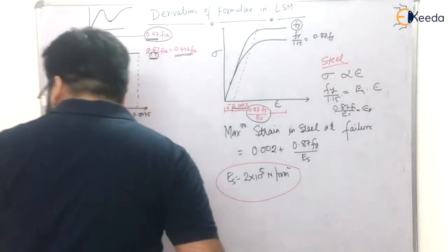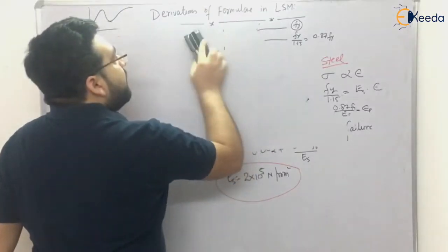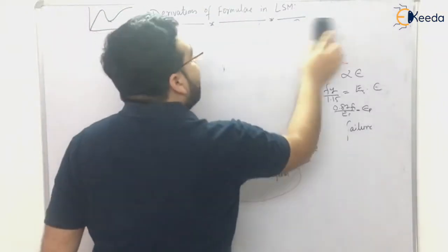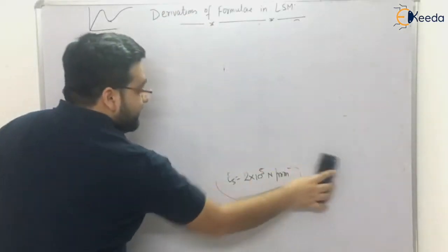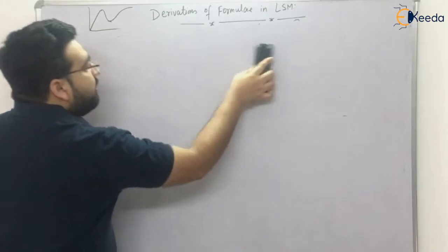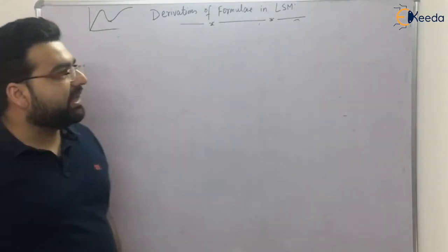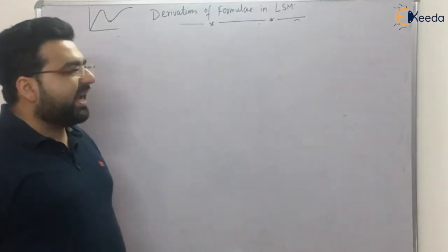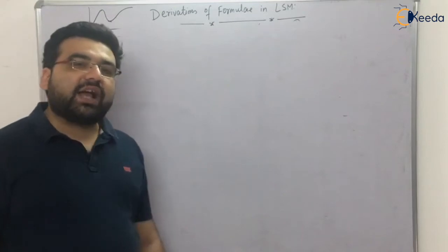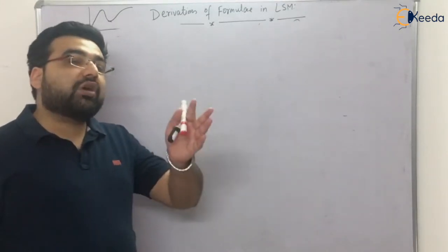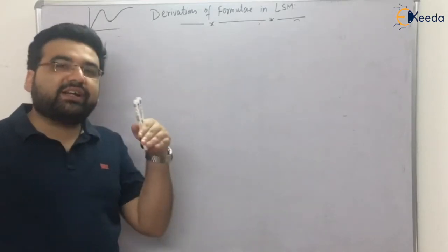So let us see the graph. I'm rubbing it. Now, till the time I rub this and start the topic, just recognize and recall that when you have to get the critical neutral axis in case of LSM, it is known as the ultimate neutral axis, XU, right? XU max. But if you have to calculate the critical neutral axis, what do you have to compare? You have to compare the strain diagram. I explained that to you, right?